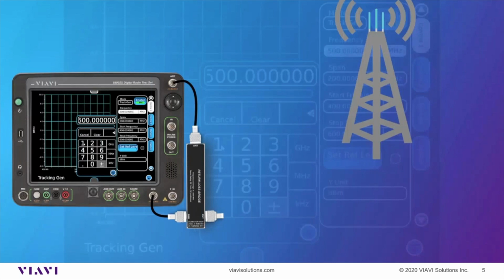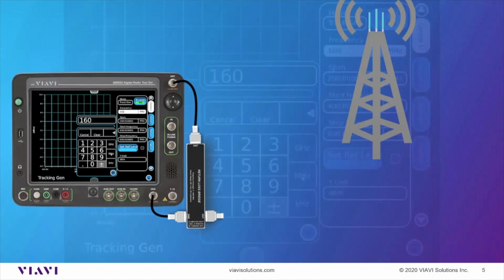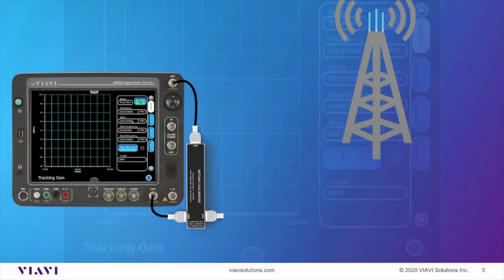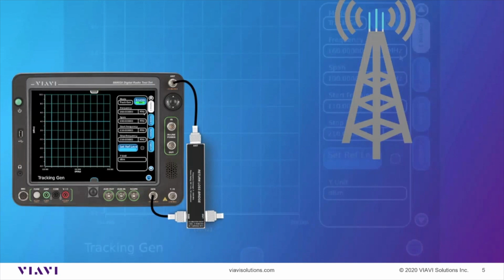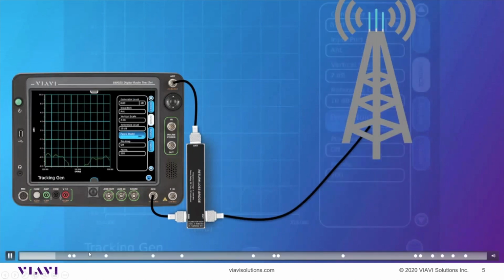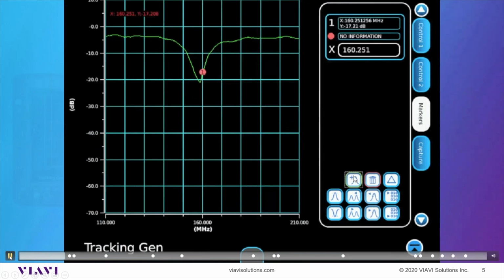Now I am going to reset my frequencies to the approximate frequency of my antenna out here, and we're going to change the span. I'm going to set it out to 100 megahertz here, because this antenna actually has a pretty wide band to it. And now we've set the reference, and we've connected the duplexer to the antenna under test. And here's what the plot would look like. This is a return loss plot.